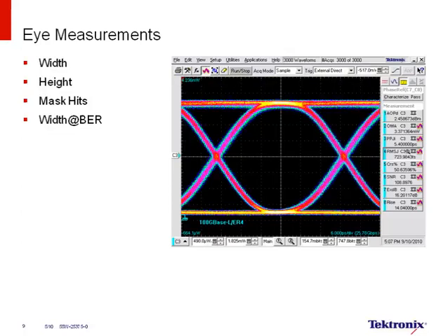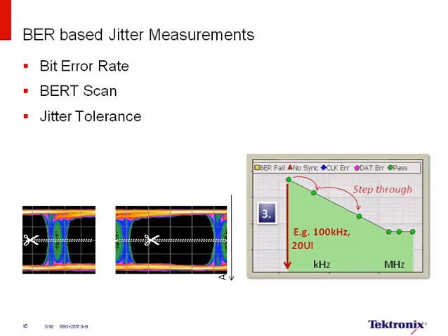In all the previous slides, we've really talked about making jitter measurements on transmitters. In many ways, it doesn't matter how low the jitter is or how open the eye is if your receiver cannot recover and open the eye. So it really doesn't matter. For example, if the eye is closed, what matters is whether the receiver can actually recover it and open the eye. So in some ways, characterizing receiver jitter can be more important than transmitter jitter.